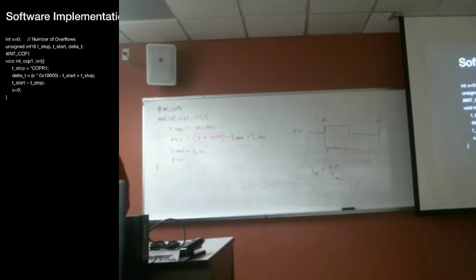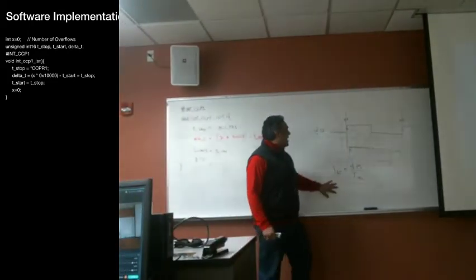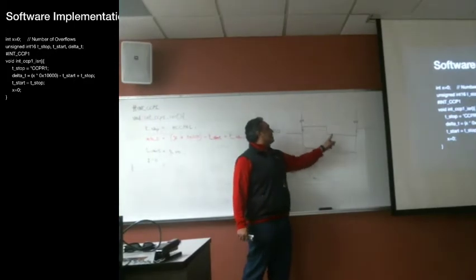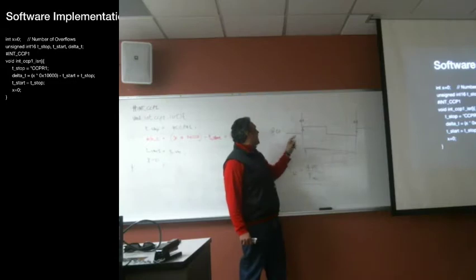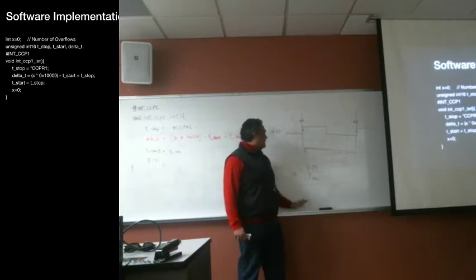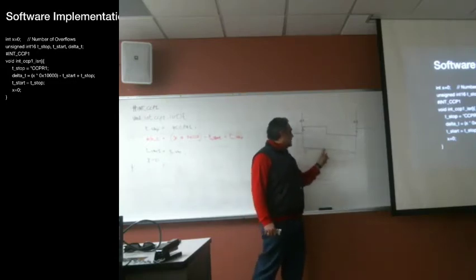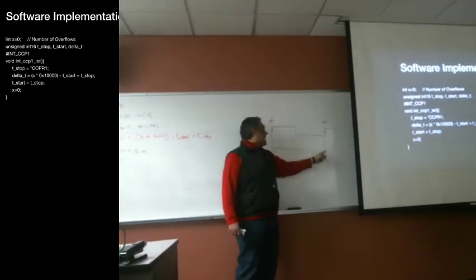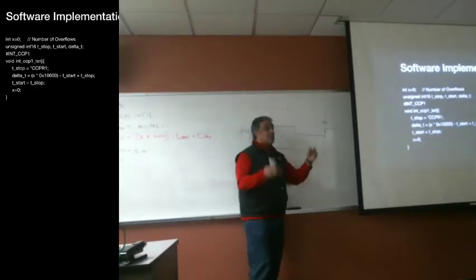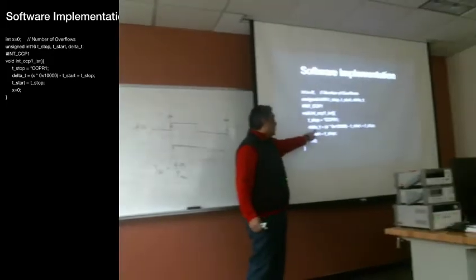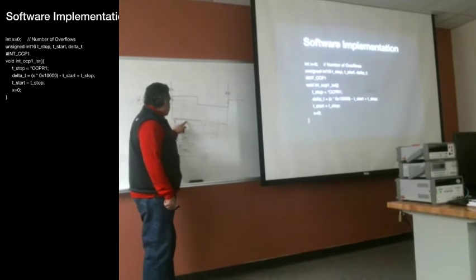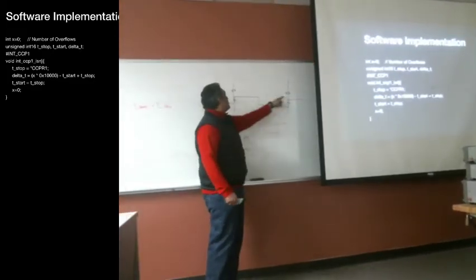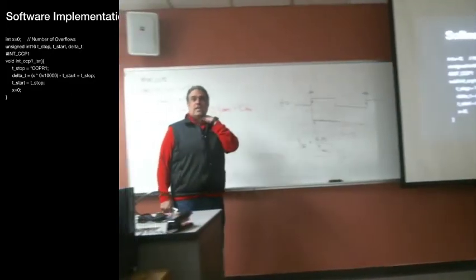So this is an interesting device. It's a very interesting device because while the events are happening at C2, every time this event happens, I'll take a snapshot and I save it. And this continues ticking, tick, tick, tick. When that event happens, I take the sample, I do the math, and this variable, delta t, will contain how many of these T1Cs occurred between these 2 events. See that?